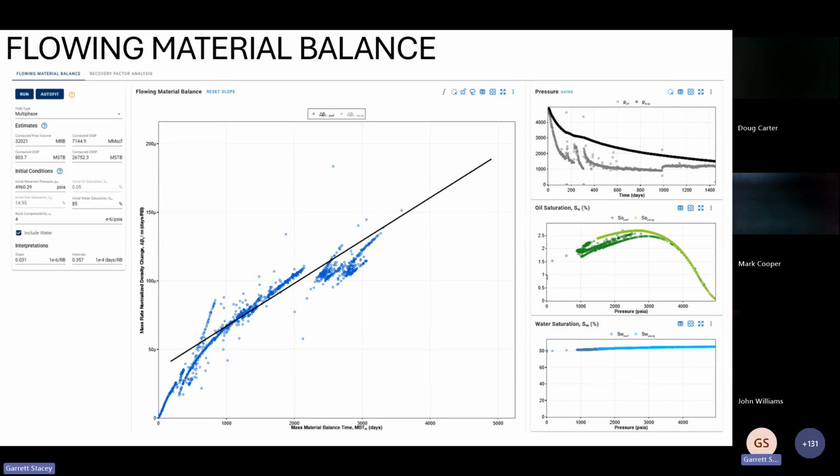And so I've had a lot of trouble getting flowing material balance curves to fit, and fortunately the bottom hole flowing pressure curve creation is very effective in Whitson, and compared to all the other gas lift software that I've tried to use, this one kind of gives you the best chance of being able to get your bottom hole flowing pressure curve over time, and then estimate your reservoir pressure and kind of reiterate until you're satisfied with it.